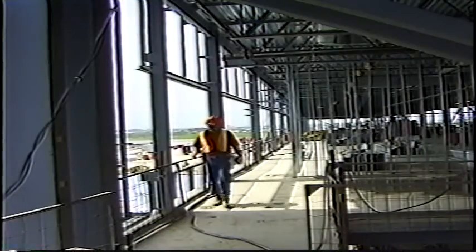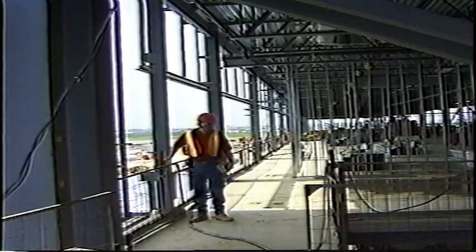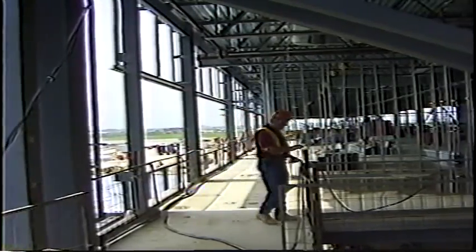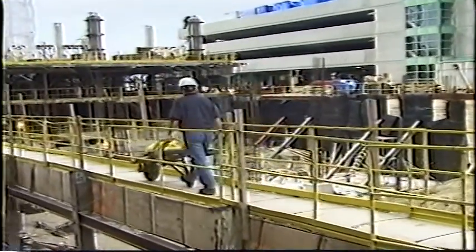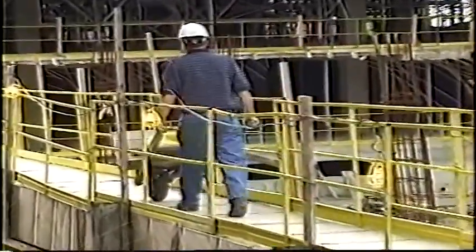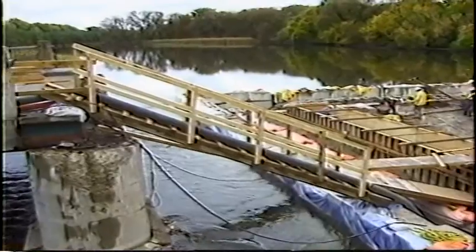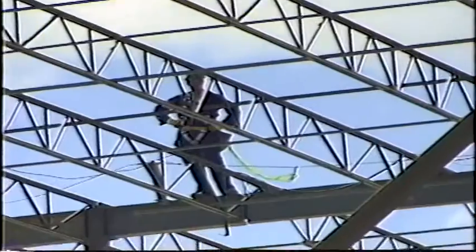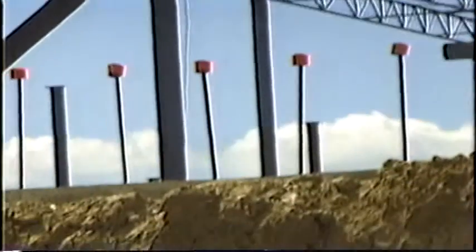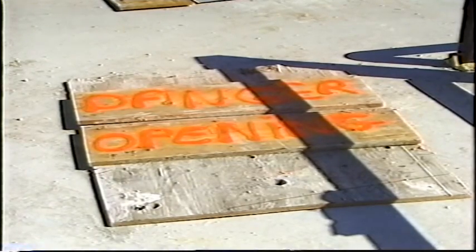The first step is to identify fall hazards in your work area. Look for situations where you could fall more than 3 meters, could fall more than 1.2 meters where the work area is used as a path for a wheelbarrow or similar device, could fall into operating machinery, or into open water or another liquid, into or onto a hazardous substance, or through an opening in a work surface.